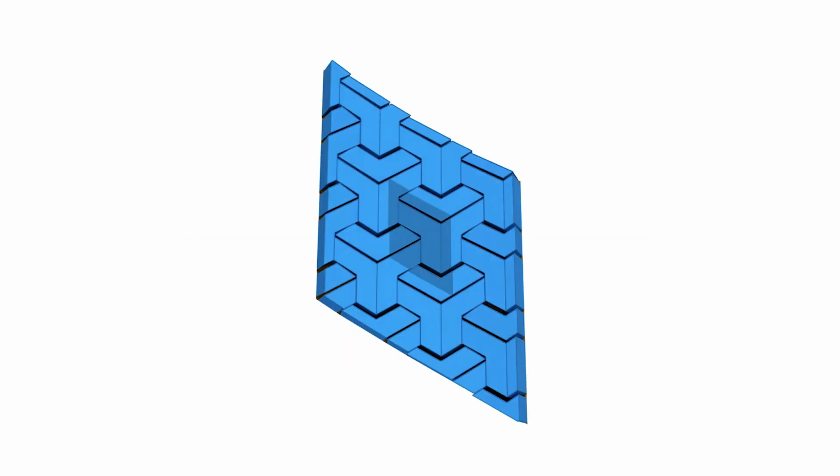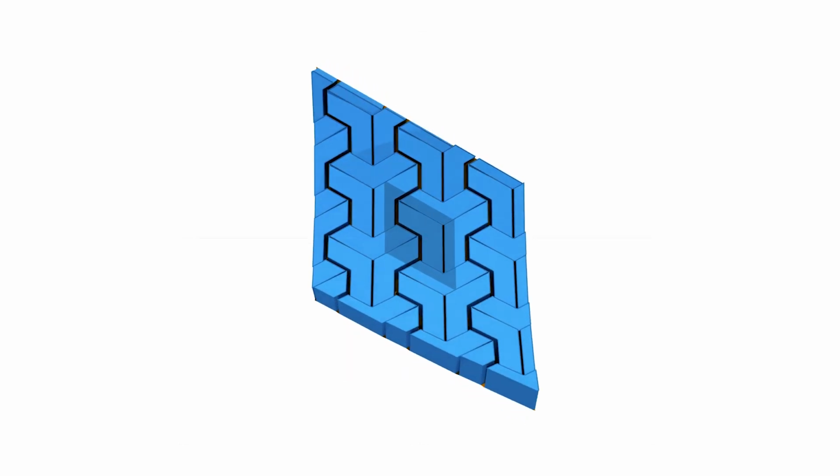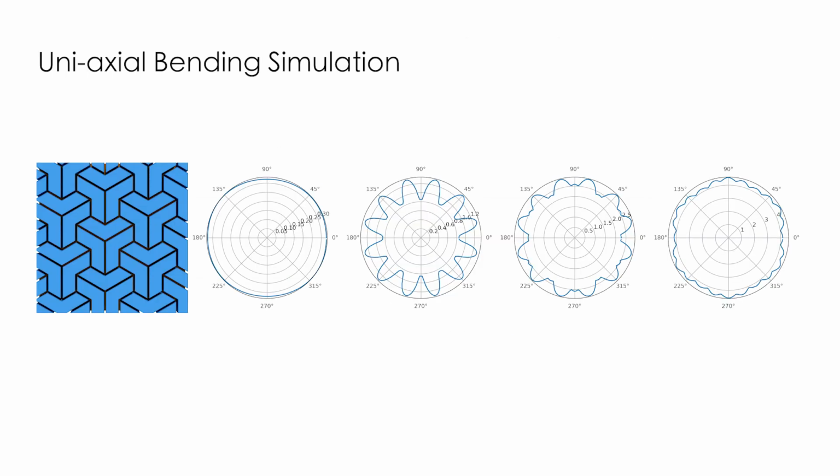To address this problem, we propose a computational approach for modeling the mechanical behavior of scaled sheet materials. The basis for our method is formed by an accurate native-level simulation model that combines soft-shell elements with hard volumetric scales and penalty-based contact. To probe the mechanical behavior of arbitrary patterns in simulation, we develop a uniaxial bending test with tailored periodic boundary conditions that generate desired curvatures without hampering in-plane deformations.